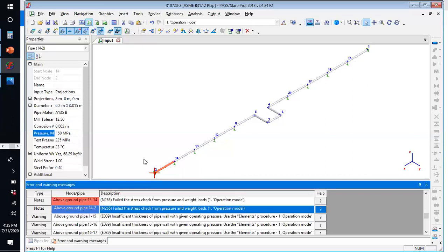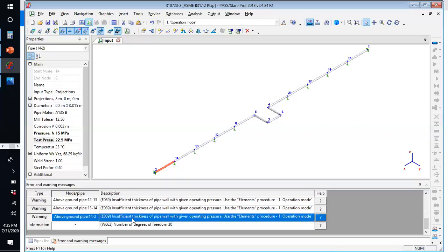And once you click on a particular pipe section, the dialog box that shows to your left represents the property of that pipe section, and you can make modifications from there. So if I make this one 15 and I make this one 22.5, that is for pipe section between 2 and 14. Then I run analysis again.